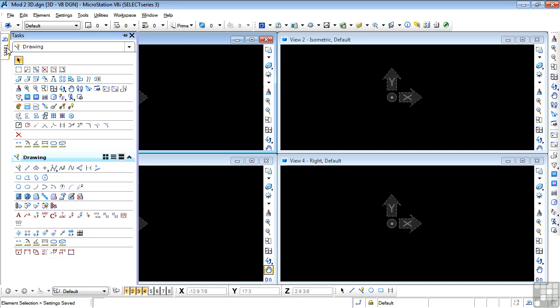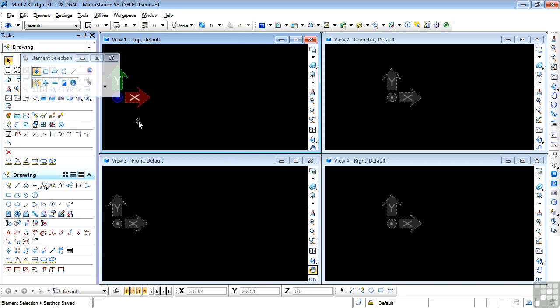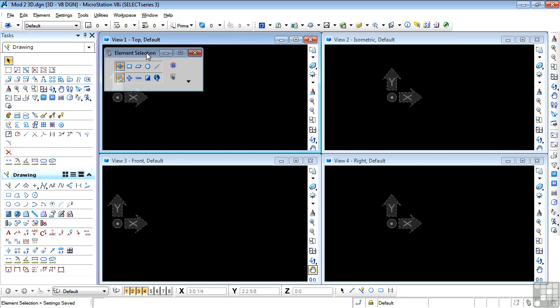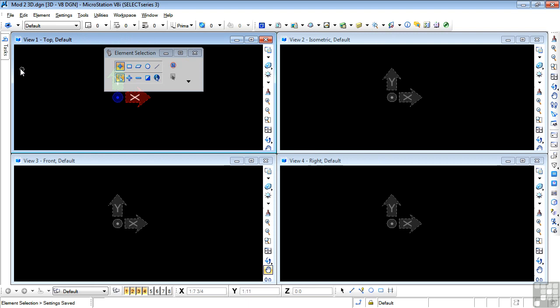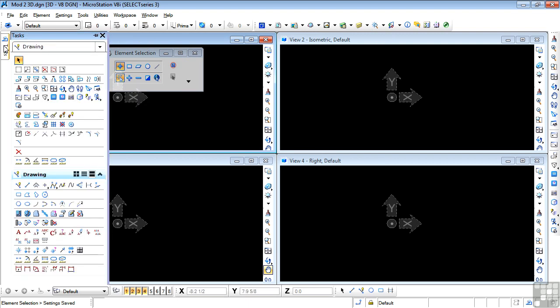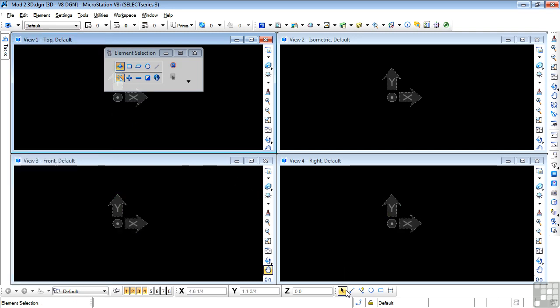The second thing to notice is that I have moved all of my editing and drawing tools to this tasks icon on the top left of the screen. I've done this because if I unpin this, then I see my toolbox sitting here, as you can see, taking up a lot of space. So to avoid that, unpin it from the screen, pops it up to there. Whenever I need a particular tool, just click on that and the tool systems pop into place. In addition, I've also added my own personal toolbox at the bottom here for my most used tools.